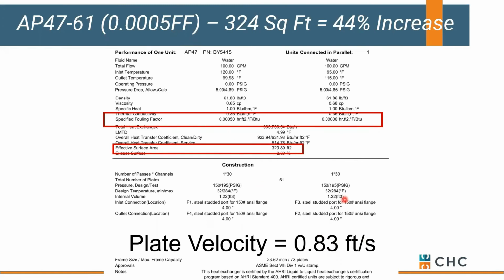Should fouling factors be applied to a plate and frame? Yes, that's the only way to account for scale buildup. You would think so, and I agree with you on this, but there's another option here. Yes, just like YouTube, a fouling factor should always be used. Again, yes, you would think so. No, excess surface area is a better option. I'm going to agree with this one, and I'll show you why in just a minute.